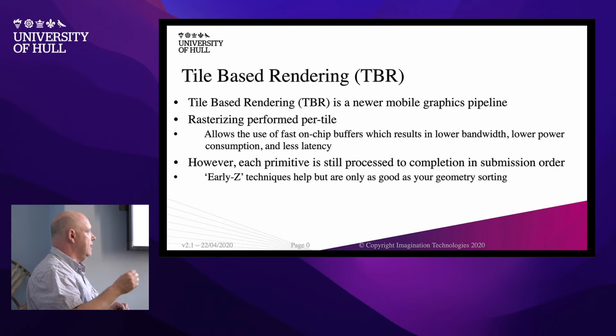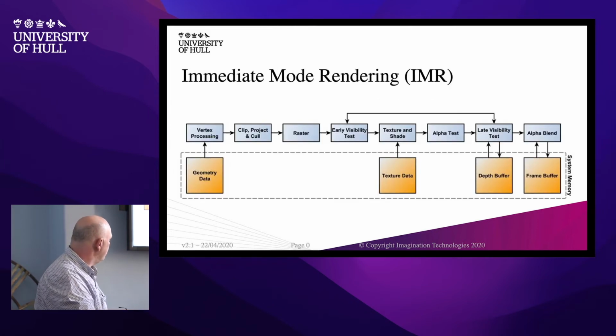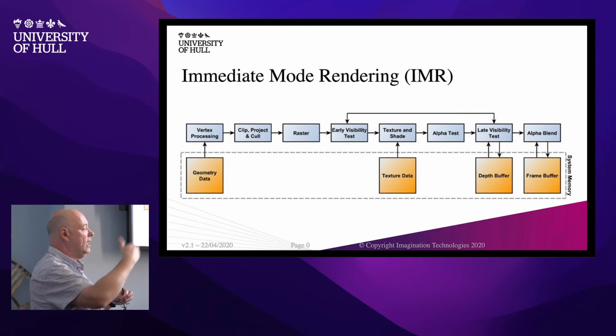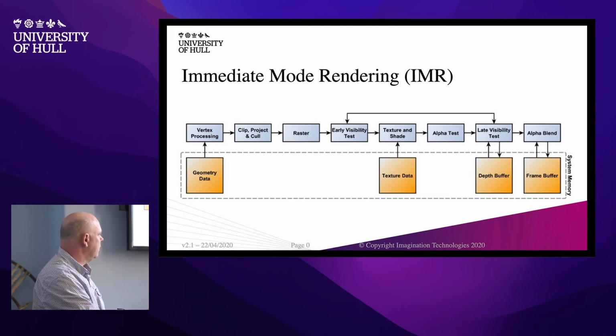What that means is, just going back to here, the reason we're using system memory is because, for instance, the frame buffer for itself, for that frame buffer to be on chip would have to be so big it would just cost too much. Okay. And again, most things come down to cost. So we just stick it in system memory because that whole frame, we cannot fit it on chip.